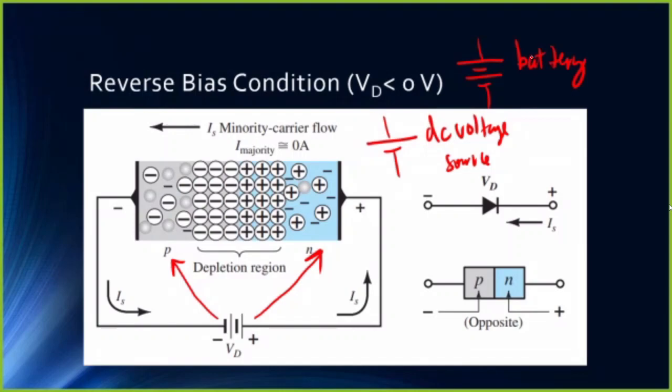Di ba ang battery, DC din naman yan. So you can use this interchangeably. Walang problema doon. But to be more specific, this is the schematic symbol of a battery or baterya. Or basically, DC rin naman siya. Okay, so negative to p-type and positive to n-type, that is what we call reverse bias condition. So the diode voltage is less than 0 volt. So ibig sabihin negative. Saan ba natin sinusukat yung diode voltage?